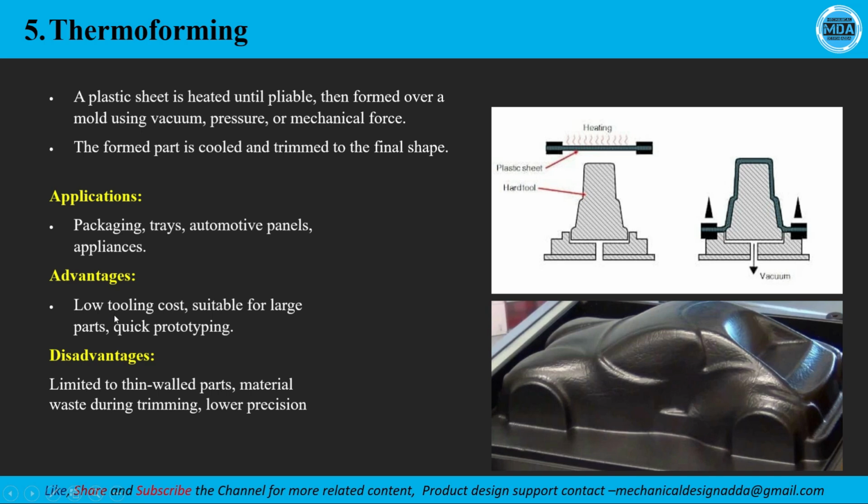The advantages are low tooling cost, suitability for large parts, and quick prototyping. The limitations are that it is limited to thin wall parts, and material is wasted during this process, so we need to trim it. And we have lower precision.